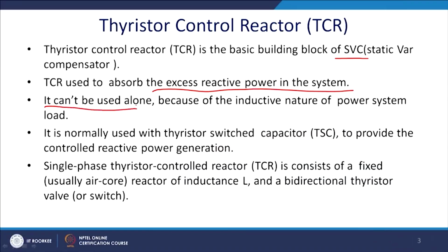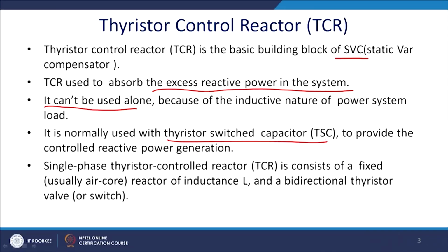Generally, it cannot be used alone because of the inductive nature of the power system load, and most of the loads are drive based and inductive in nature. It is normally used with a thyristor switched capacitor to provide controlled reactive power generation.